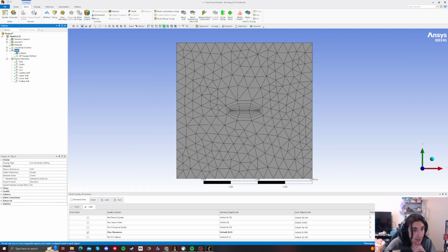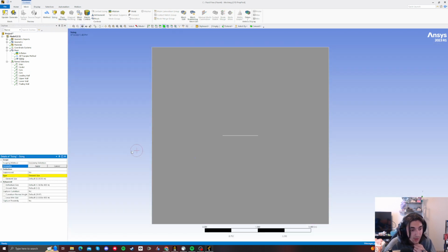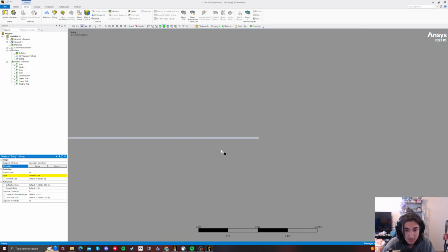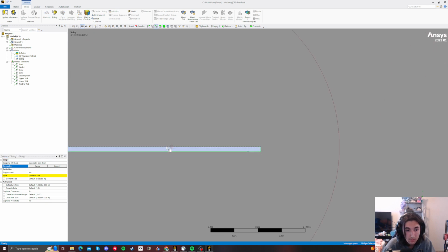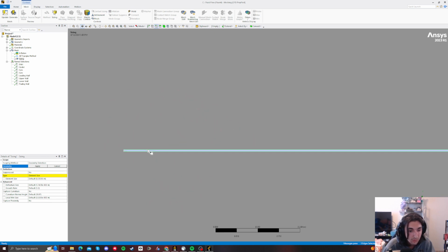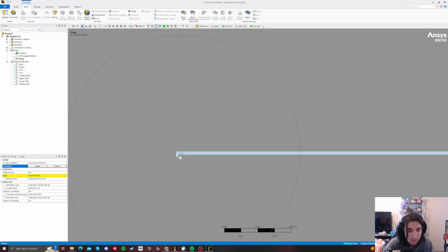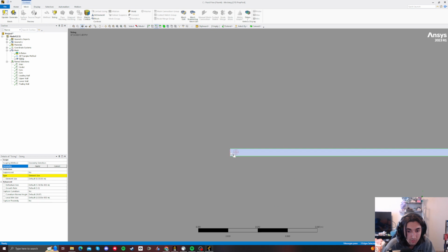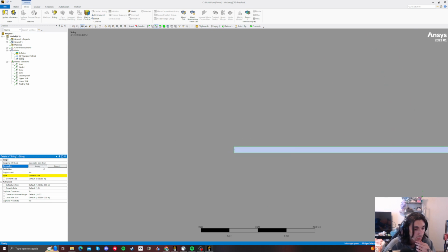Now we're going to do a sizing edit. So you click sizing, and then you're going to do your geometry selection again. Can I select this, please? Oh, edge select. I guess it is necessary. Okay, and then hit apply.